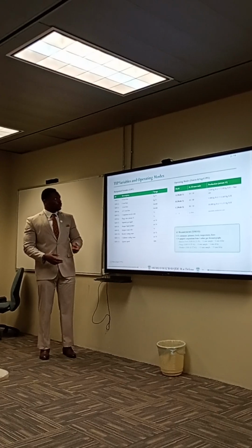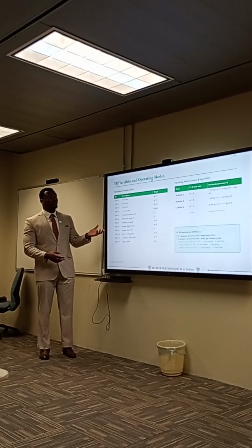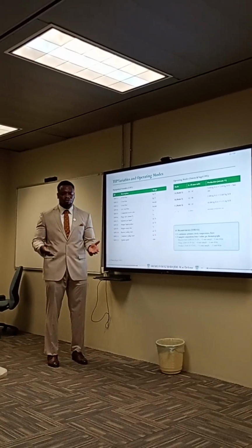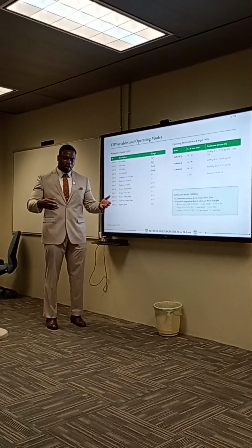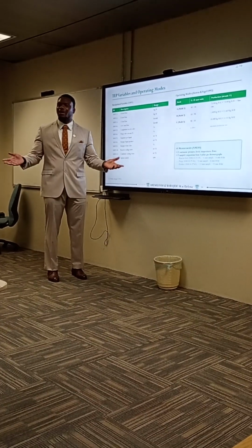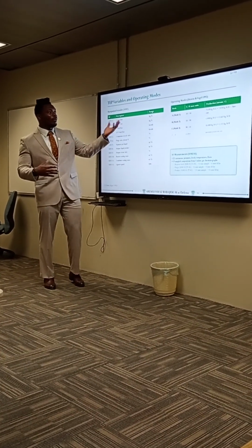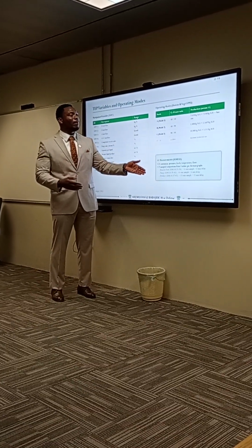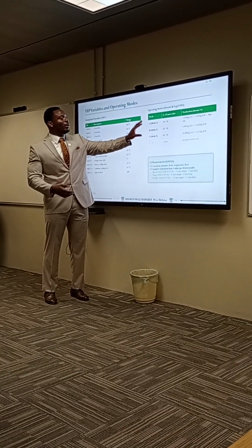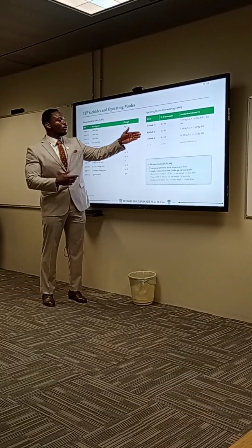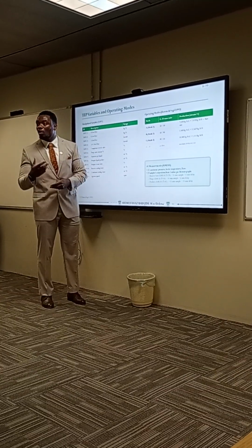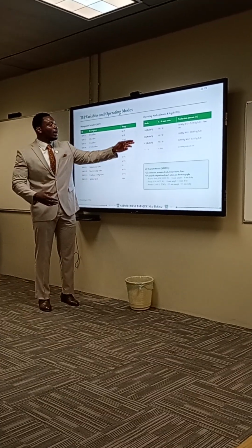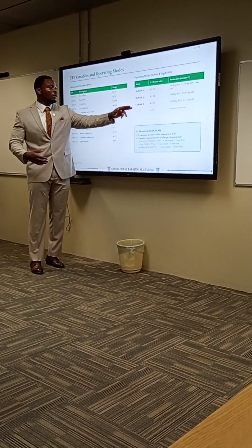When we look at the variables, you have 6 modes of operating a plant. Usually, if you go to a refinery or a production factory, there can be several modes. The Tennessee Eastman process operates on 6 different modes. Modes 4 to 6 are maximum production rates, but we're considering just the first 3 modes, which are based on the quality of what we produce in our plant. Basically, we have 50-50, which is the G to H ratio, 10 to 90, which is low, and 90 to 10.